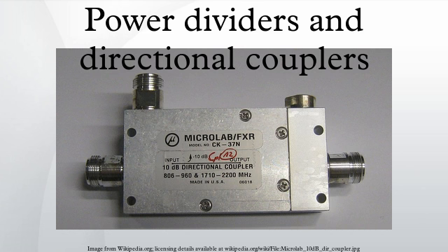It is, however, possible with 4 ports, and this is the fundamental reason why 4-port devices are used to implement 3-port power dividers. 4-port devices can be designed so that power arriving at port 2 is split between port 1 and port 4 and none goes to port 3.